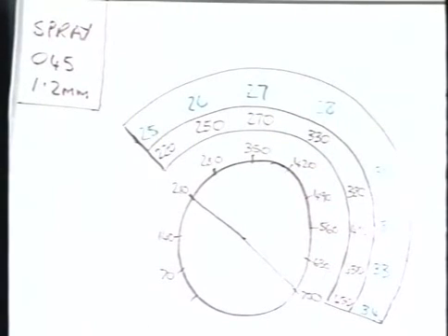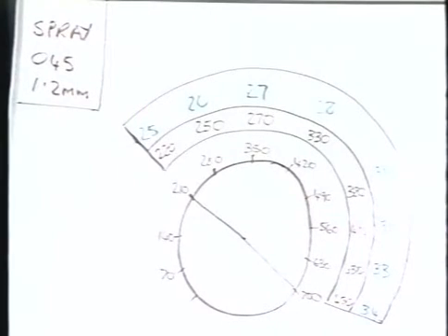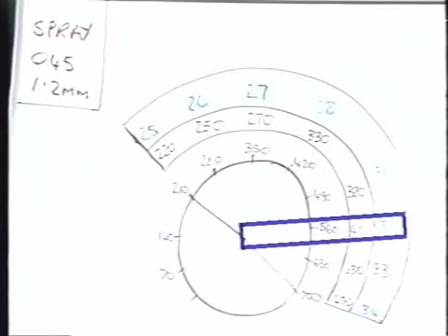An ideal starting point with the 045 wire would be approximately the 2 o'clock position. You want to be somewhere between 400 and 500 inches a minute. Do you remember with the 035 wire, it was in the range of 500 to 600 inches a minute. The 045 wire in the range of 400 to 500 inches a minute, between the 1 and 2 o'clock position, is again an ideal starting point on 1/4 inch. If you need to go to 3/8 steel, then you would traditionally be again at the 3 o'clock position.